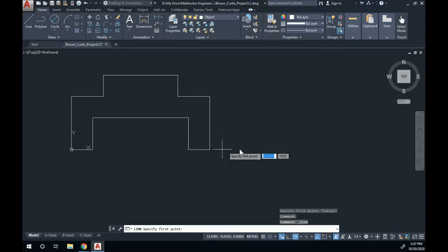If I wanted to line up on the same plane, like if this was a level surface going across, I want to place that. Let's say I want to place it right there. Notice my crosshairs are like 15.5 for X. I'm going to type 16, and I'm going to tab over, and I'm going to type 0 because I want that to be right on the X axis. So at least I know that my two objects are going to be lined up at the bottom there.